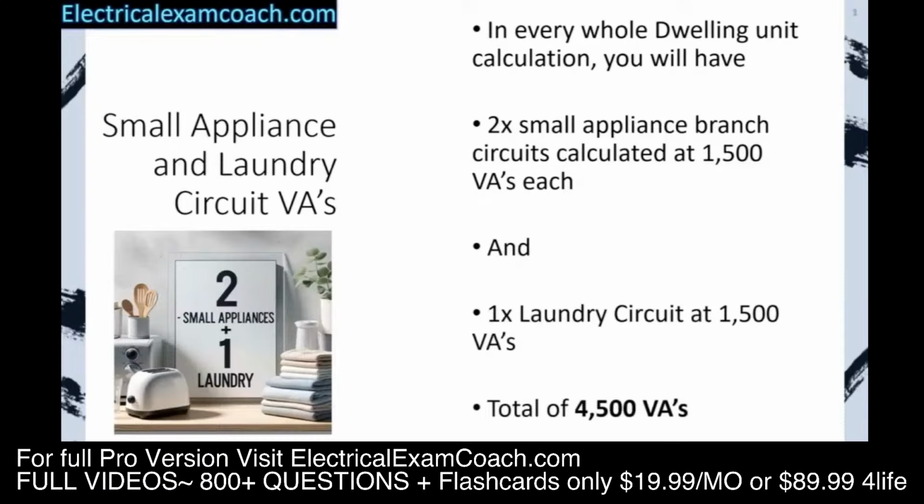Now, this is something that we're only going to do and attach to the general lighting load and receptacles before demand factors. We're only going to do it when we're doing a whole house load calc. We are not going to add it on to something like an individual dryer or an individual range. Those are calculated individually. This is only when we're doing a whole home load calc. And once we start doing them, I will make sure to reiterate to you so you understand when and how to apply this.